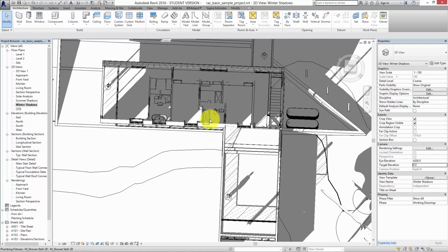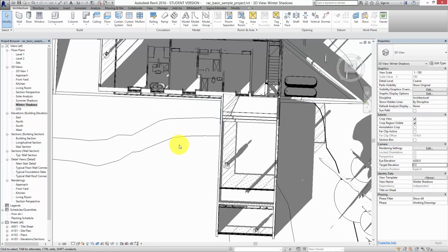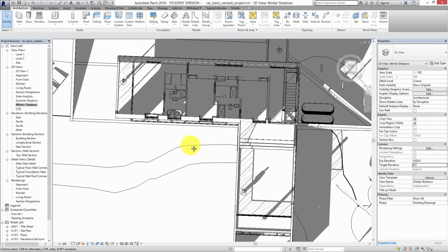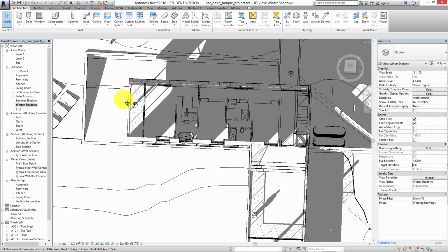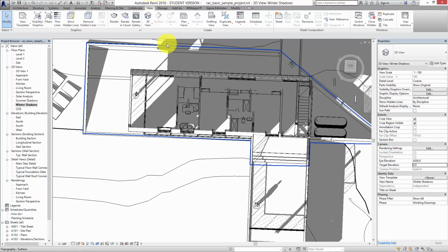But often when you're designing a concept house, you need to know more or less what the light is going to be like. Now you can usually get a sense for it after a certain amount of time, but sometimes you need to convince other people who can't read drawings, like planners or clients, as to how much the light is going to be like in the house. In Revit we have this cloud render thing. If we go into view and we go into rendering cloud,